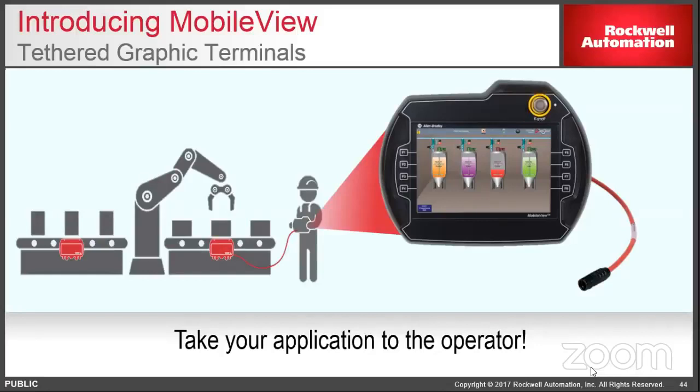What this basically is at its core is a PanelView Plus 7 type product. It runs PanelView Plus 7 applications, PanelView Plus 6, it runs FactoryTalk View Machine Edition, and it's a handheld unit. So why is it handheld? It's for applications where you potentially need line of sight to a robot arm or other machinery that you want to position. You see it's got an e-stop on there. It's got a hardwired e-stop. It's got hardwired enabling devices built into the handle, sort of like a dead man switch. So once that's programmed in as part of your safety solution, you can rely on those as a SIL3 solution to get back to a safe state.